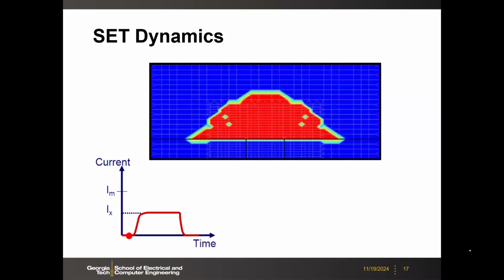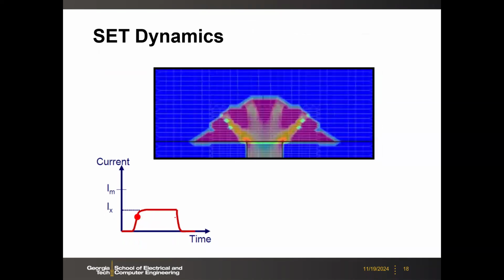And then the set, which is the other way around, we have to apply a low current profile like this. Okay. So then you see that there will be some conduction path through this amorphous state, and then there will be current flowing through, but this current amplitude is small, so you will locally heat up a little bit.